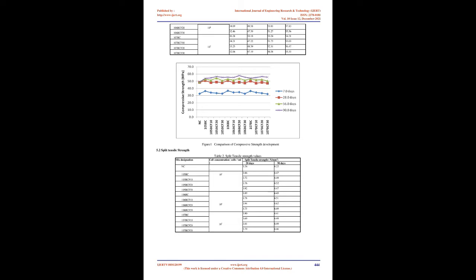Bacterial spores are specialized cells which can endure extreme mechanical and chemical stresses, and spores of this specific genus are known to remain viable for up to 200 years. Spores are dormant but viable. Bacterial spores immobilized in the concrete matrix will become metabolically active when revived by water entering freshly into the concrete.